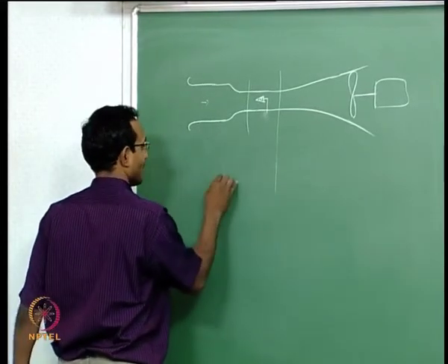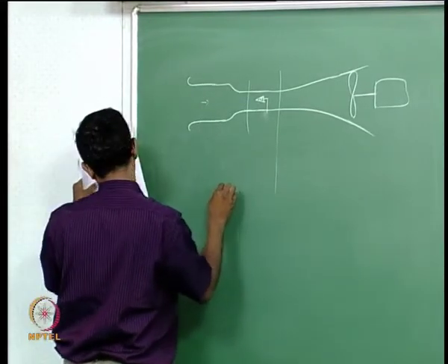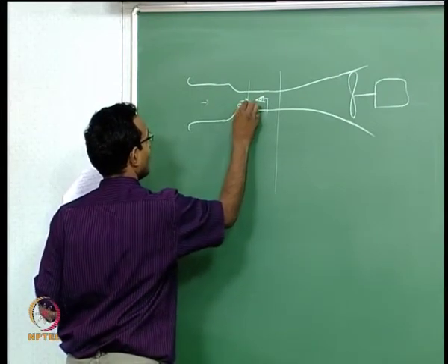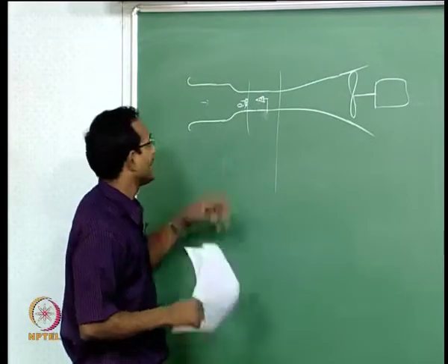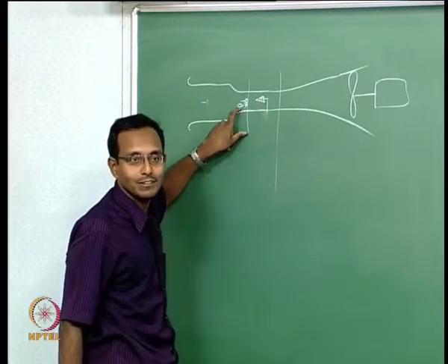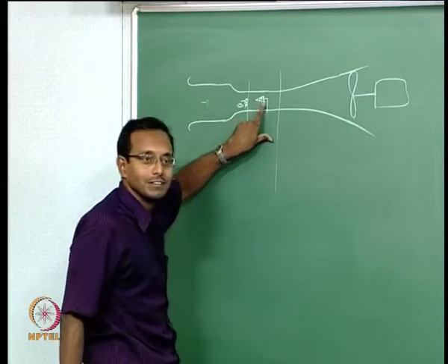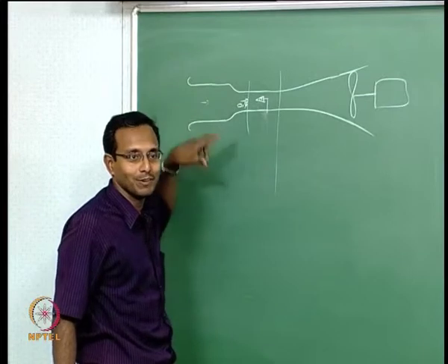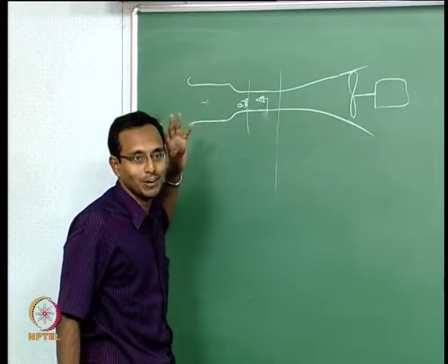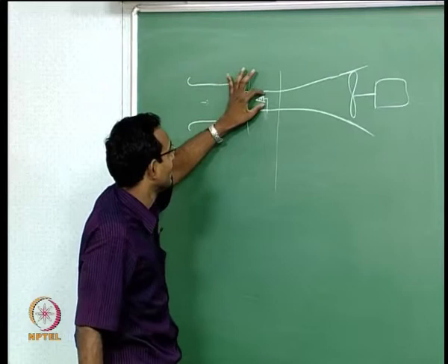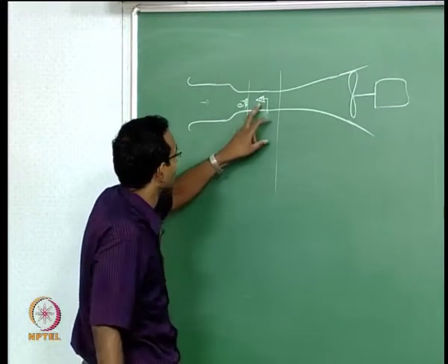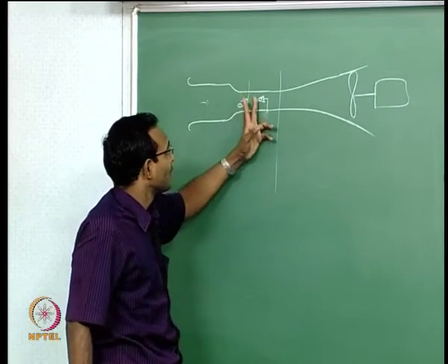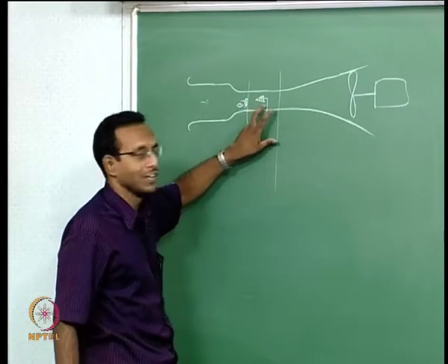I am thinking about a Mach number 0.9 where I want to do the experiment. If I think about Mach number 0.9 here, then it is going to have choking, right. Any small area change, if you look at A by A star for Mach 0.9, it is going to be close to 1 already, and if I change the area much more, then suddenly there will be choking in the middle. And now that flow cannot go through because it is choked and I am still changing area.